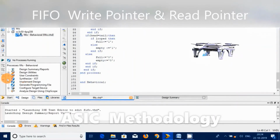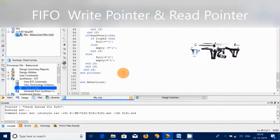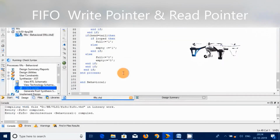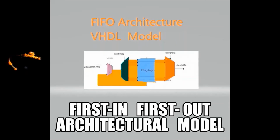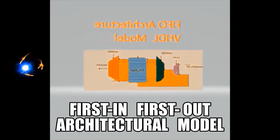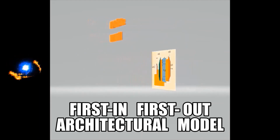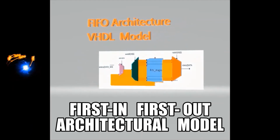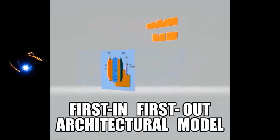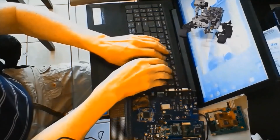In the dual port RAM model segment of the FIFO, it uses a write counter to address the write side of the RAM and a read counter to address the read side of the RAM. The control logic updates the write counter at each write of data into the RAM, and the read counter every time data is read from the RAM.